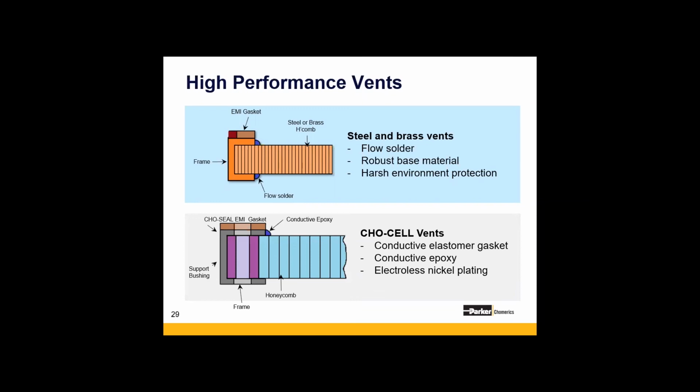So steel and brass tend to be used in a lot of military enclosures, communication shelters. Anytime you hear designing something for EMP hardening or Tempest equipment, you're going to think stainless steel or brass, especially in extreme environments where weather or salt fog, salt spray is an issue.